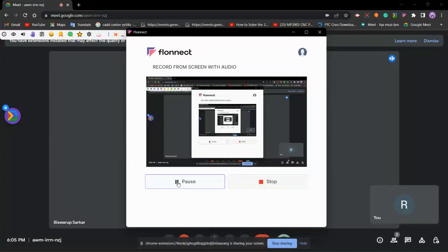Exit. Select the sketch. It is extruding normal, perpendicular to the direction of the plane in which it is drawn, always. But if I have a reference direction, for example, I'm selecting this edge as a reference, you see, it's extruded in that direction only. Understood?